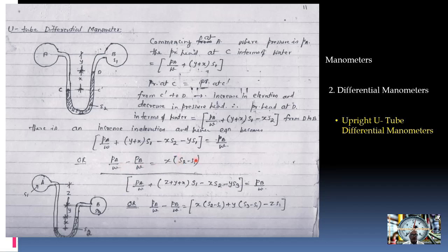In case of mercury and water, let us say the example of mercury and water we will very frequently use in fluid mechanics 1, 2. So Pa by W, the pressure head at inlet, and PB by W, pressure head at the throat. Let us take the case of the venturimeter, and H dash is the difference in height, manometric level difference.